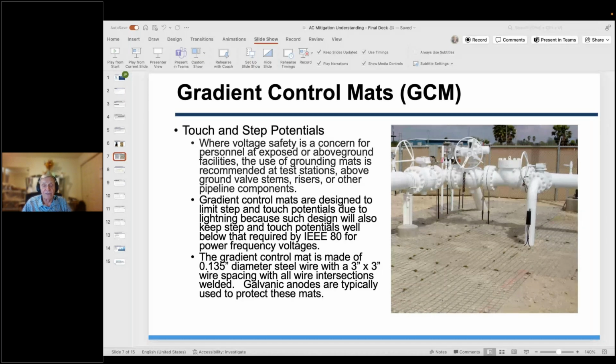A good deal of it goes down to the shield wires and spreads out that way and tries to go back to the substations and things of that nature, or additional grounds along the tower line. So how it goes, depending on the resistance, the maintenance of the shield wires, the maintenance of the grounds, all play a big role. So when we calculate, and we're going to get into that in a minute. The next slide, Nick.